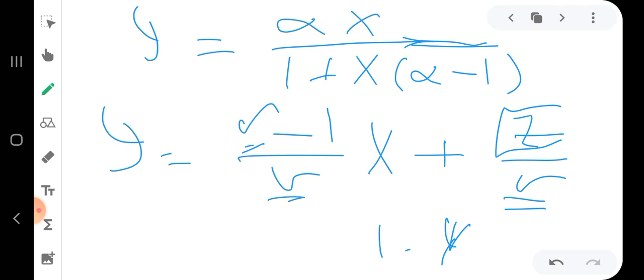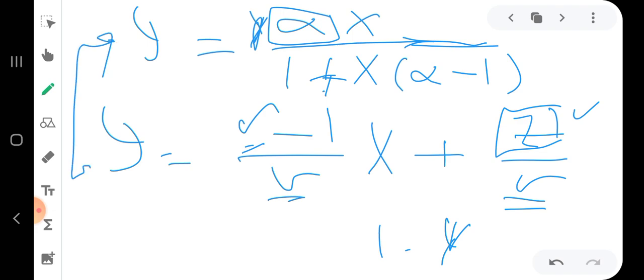Okay, and usually the composition of the feed is given. Okay, and usually the relative volatility is given, and after a while we will talk about the cases where the relative volatility is not given. But now let's suppose that the relative volatility is given. So you can say that we have two equations, equation 1 and equation 2, and we have two variables, y and x. Two equations, two variables, so I can solve them simultaneously.